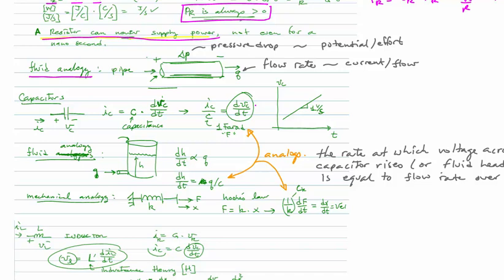In real fluid systems, although we might say roughly that the flow rate, that's like the current, is proportional to the pressure drop. In fluid systems, that very quickly becomes nonlinear and not a nice proportional relationship, but in certain constrained conditions that is true, and so that works as an analog to resistance and electric current.